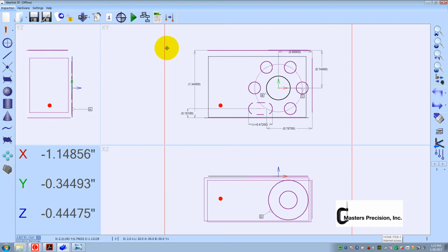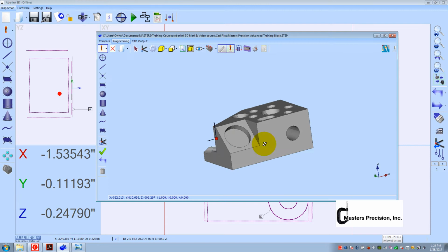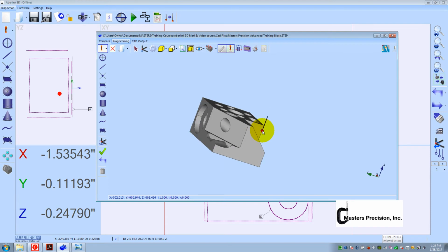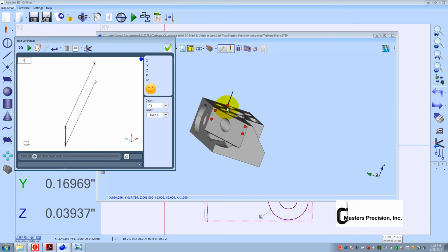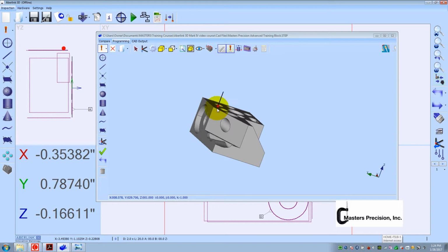So now I need to measure the angled line. In order to do the angled line, I need to choose the right probe. So I'm going to go negative Z, which is pointing straight down. Just measured a plane there. Selected OK. Now while I'm over here, I could actually do that 60 degrees and that angularity, but I got to get this plane measured here.